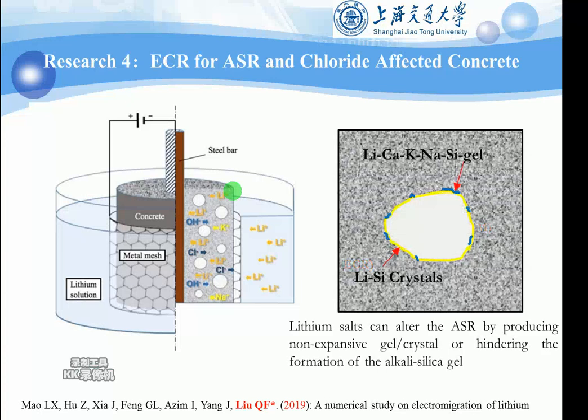This is because the lithium source can alter the ASR products by producing non-expansive gel or hindering the formation of the alkali silica gel.